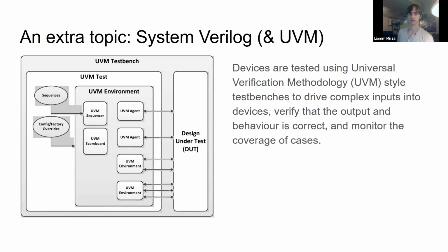Yeah, even with an ASIC, which is application-specific integrated circuits, so stuff like processors, there is an FPGA step after all this UVM stuff is done. So they'll take the DUT and put it on an FPGA and then test it again that way, just to ensure that it works physically. So they have a lot of steps, because once you print the chip, you can't recall it, because you spent millions of dollars already to manufacture it. So yeah, it's a serious problem when that happens.